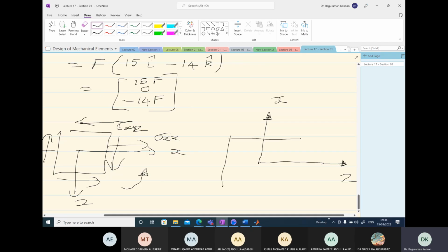Again, draw the stress element, but this time be careful in denoting the directions of your shear stresses correctly. On the plane perpendicular to the x-axis, the shear stress is in the clockwise direction here. With respect to the z-axis, it is in the anti-clockwise direction. Now it is right. Clearly, this is a positive shear stress value. We have the sigma xx value here.